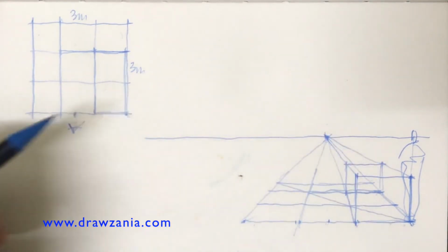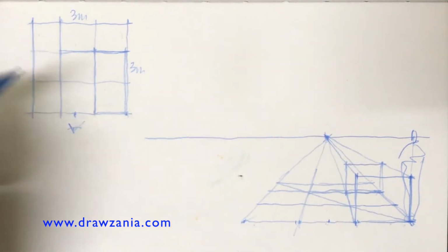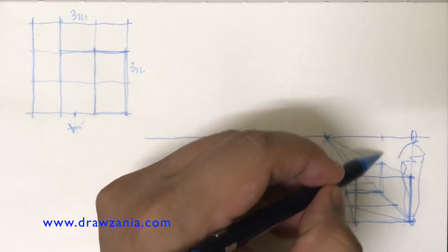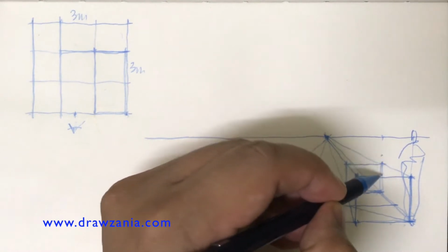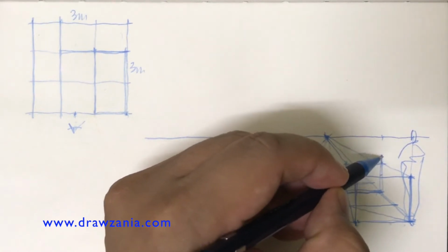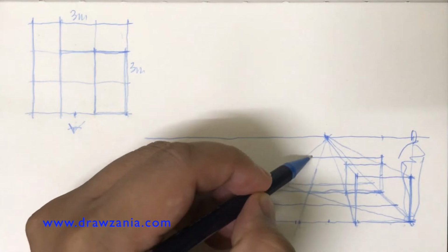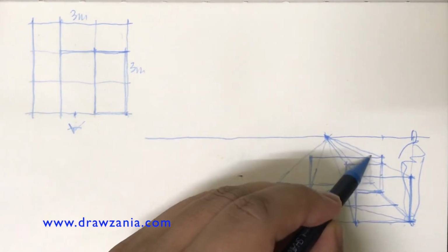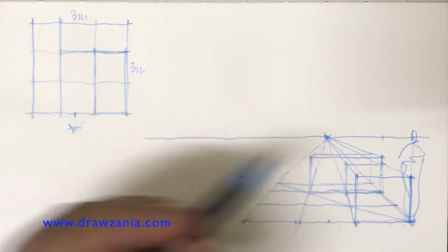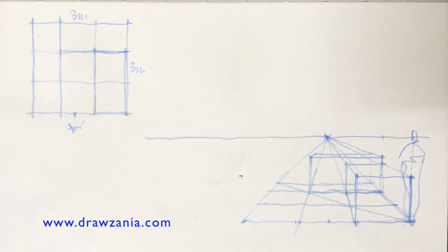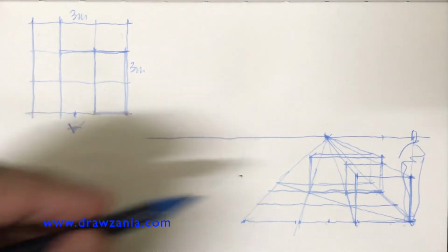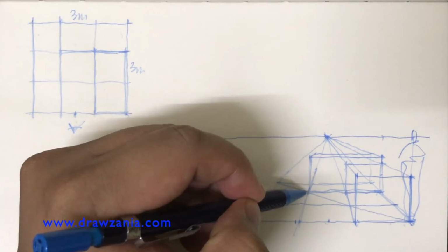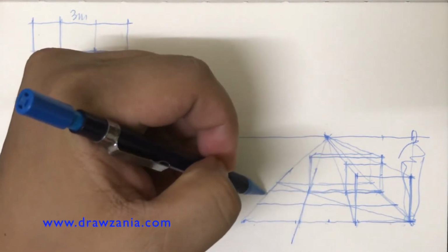And then you continue again to draw your planter box with a height of 1 meter. You know that from here to here is 1.5, then you divide it into 3, and that is your 1 meter. Then you have a 1 meter planter box somewhere there, and then you project that line. That is your planter box. Okay, where's your pathway? That is your pathway. You can see that this is behind the planter box, then that is your pathway.